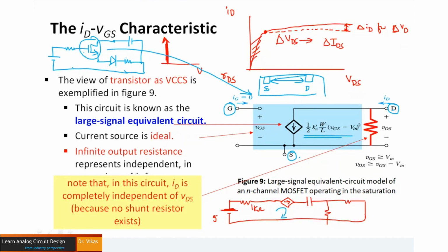So that means if you see this particular MOSFET, I have a gate, I have a source, I have a drain. So wherever you have a GDS, just try to connect that over here. And now if you see this entire MOSFET, this entire new network would be changed into completely passive components. So that's how you can apply your KVL and KCL. So is the case with your diode. Diode also comes with its own model. You can replace that with that particular model. So that is how this particular thing is observed.